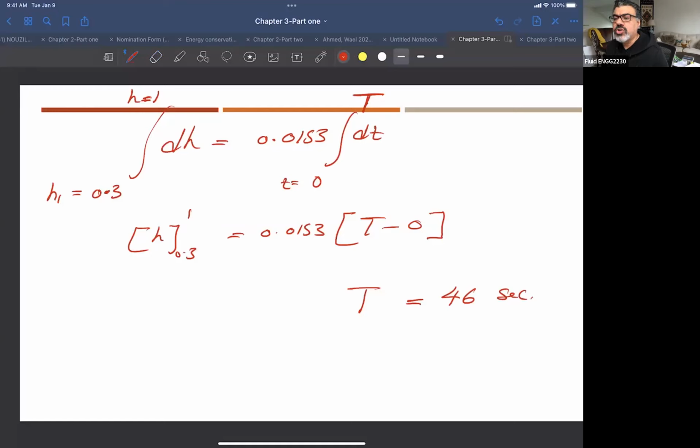Yeah, the pressure here has no effect on our calculation. We're talking about mass, right? So whatever condition coming in and going out, the difference between the flow rate in and out will be basically filling the tank, right? Of course, in reality, if you are observing what's happening, you might see less flow coming in because of higher pressure at the top of the tank. But this has nothing to do with the analysis here.